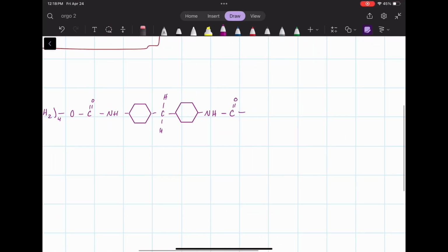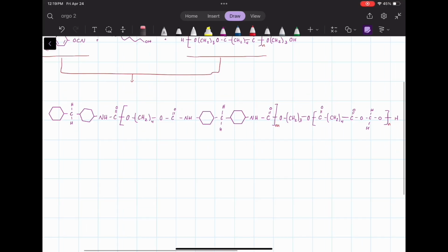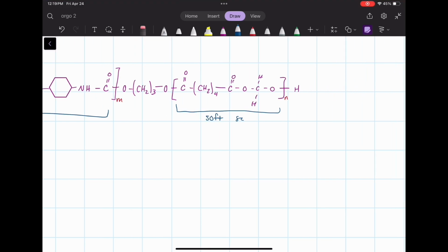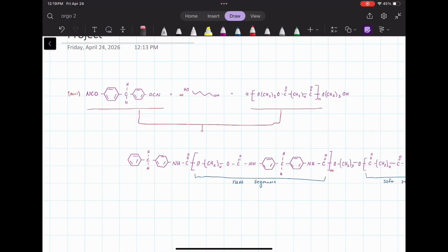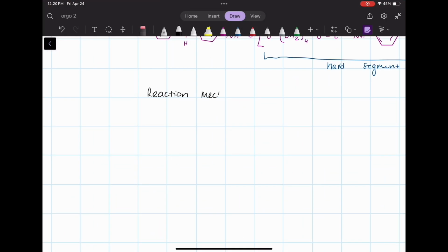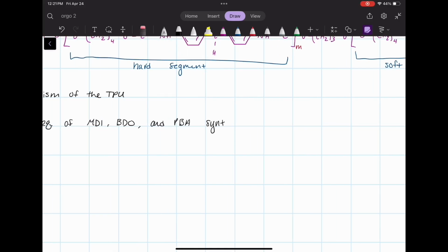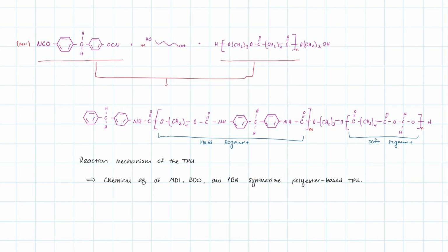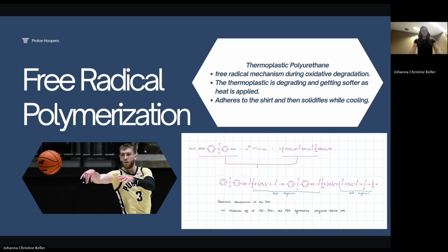Oxidative degradation is the chemical breakdown of materials. This happens primarily with polymers, plastics, and fluids. This happens when it is reacted with oxygen. It is often accelerated by heat, light, or stress. In our example, we are using heat. It involves free radical mechanisms that cleave molecular bonds. The cleavage of these bonds reduces material integrity and causes discoloration, surface cracking, or increased fluid viscosity.